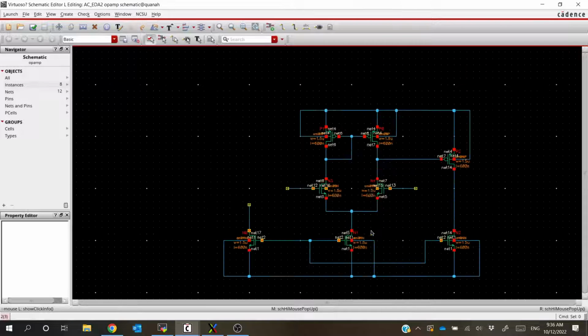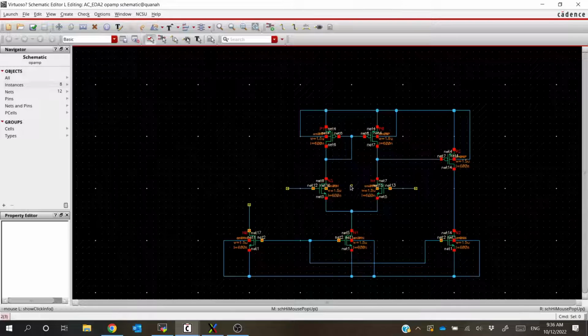Now, we're going to come back to this, but really quickly, I want to talk about the workflow of working with Cadence. Typically, whenever you're working with Cadence, you want to abstract problems as much as you can. So you want to start small with very small cells, and then as they get larger and things become more and more integrated, you want to be able to work with these smaller cells to abstract or model a problem differently.